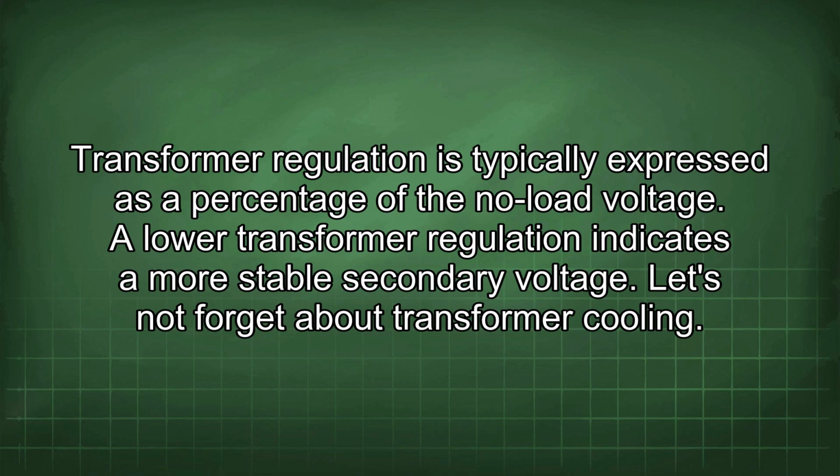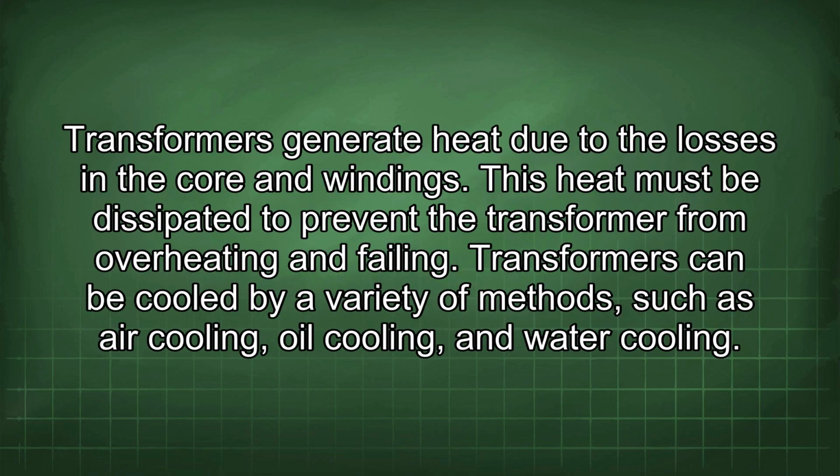Let's not forget about transformer cooling. Transformers generate heat due to the losses in the core and windings. This heat must be dissipated to prevent the transformer from overheating and failing. Transformers can be cooled by a variety of methods, such as air cooling, oil cooling, and water cooling.